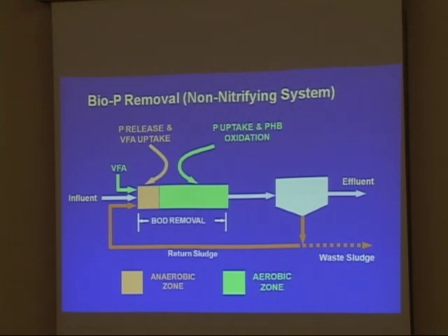One of the things that could screw up your capture of the phosphorus would be the conditions under which the phosphorus is stored, because you can get a re-release of the phosphorus if they're put into an anaerobic condition. They get stressed, and all of a sudden they drop it all off again. So if you monitor side streams, if the bugs aren't getting produced quickly and they're sitting too long, you will have the phosphorus really released in the supernatant or side streams coming from solids processing. Just a thought, and I don't know if you can answer the question, I know I can't answer the question.